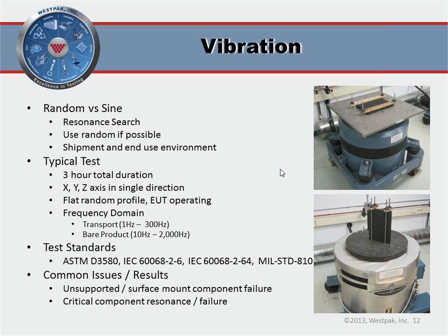And then the last thing, especially with larger products, is be careful with unsupported large components. So things like capacitors, heat sinks on circuit boards, especially if they aren't through-hole or surface mount. Anything large and unsupported that hits a resonance, like Herb was talking about, comes off.